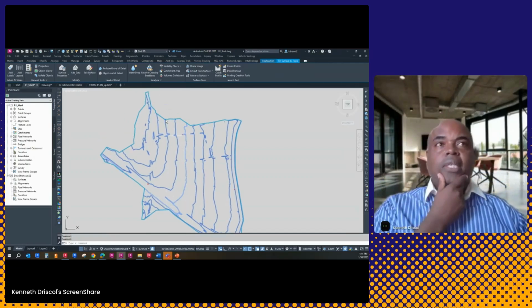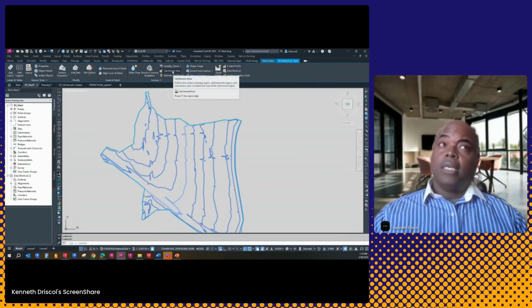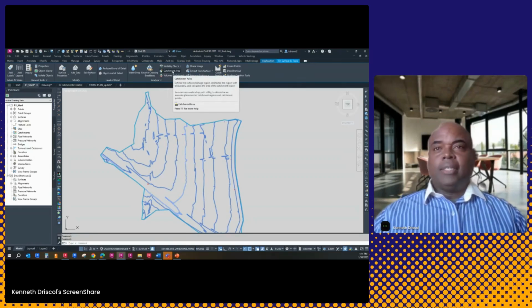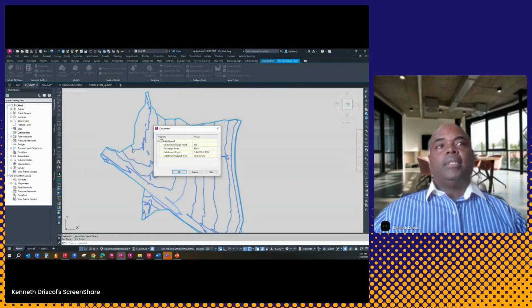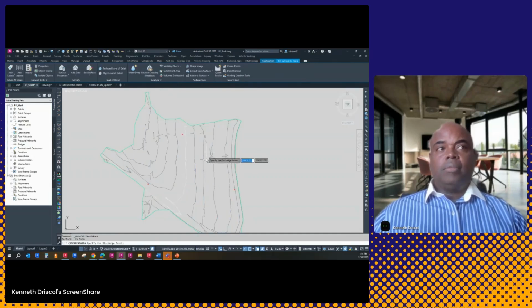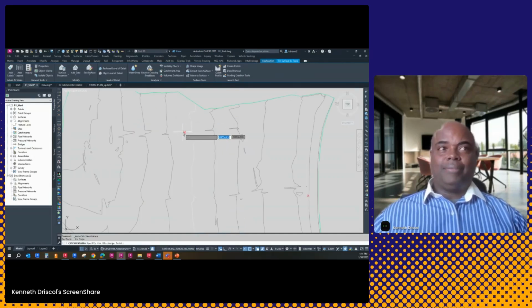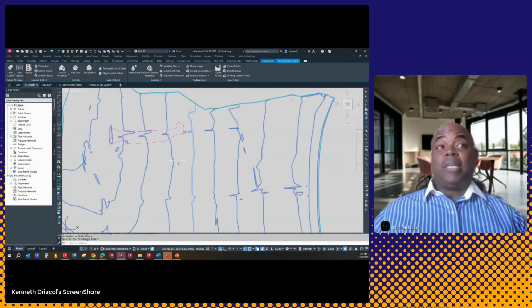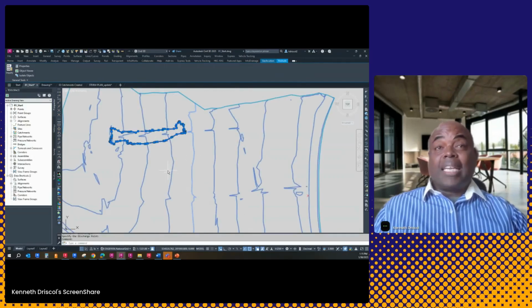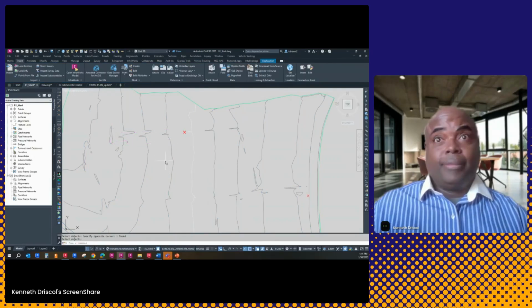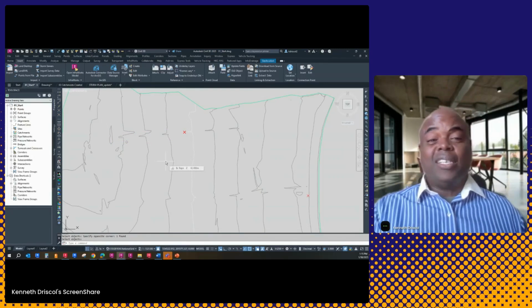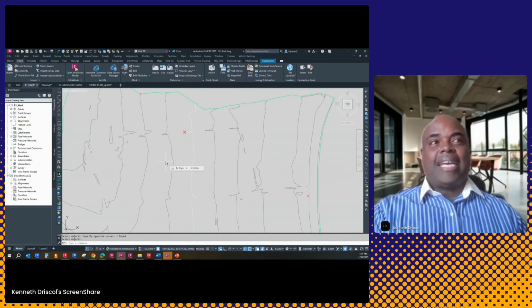So with Civil 3D, we looked at this little item right here. This catchment area, it's really not for modeling. Now, years ago when we wanted to generate a catchment area, for instance, if I go in and select catchment area and I pick a specific point, it gives me a catchment area. But it doesn't give me anything. It's just a polyline, which is why in the PowerPoint I put, really don't need to use it, because you can't use it for modeling unless you add some information and data to it.